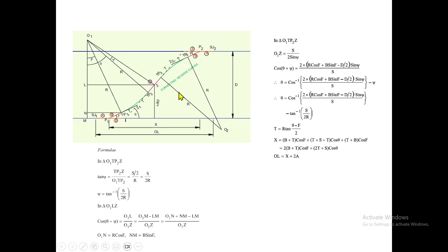Anyway, we don't go this side because we want to resolve everything up to this point. But we need to know this angle, because this angle is theta, so that we'll be able to get this triangle. By taking this triangle, we can find out the horizontal distance. So now we have theta and the deflection angle, everything. So now we can try to find out the x. From here, we make this triangle first.